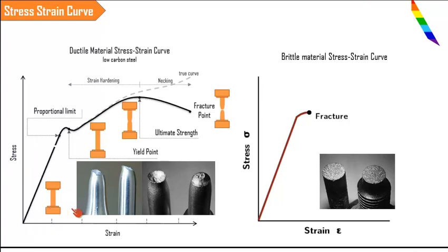I hope you all remember in the first class I told you that the strain is a physical phenomenon or a geometrical phenomenon, and it can be measured experimentally. You cannot measure the stress. So the same thing is happening here. We are not measuring the stress, we are measuring the strain. After measuring the strain, using the constitutive relations, we calculate the stress. So that is a very important thing that all of you should keep in your mind. Now let us see what the salient features of the stress strain curve are.